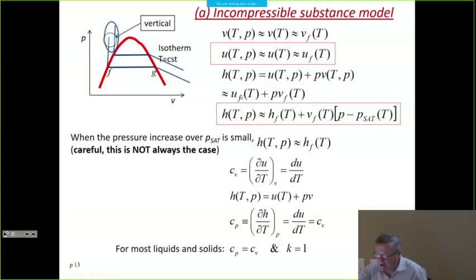We just need to look at temperature. And since the line is vertical, we can just look at the value in the saturated region. So when you're looking at an incompressible fluid for a specific volume, you can take the one at the saturation temperature. The same with the internal energy. It is the one at the saturation temperature.